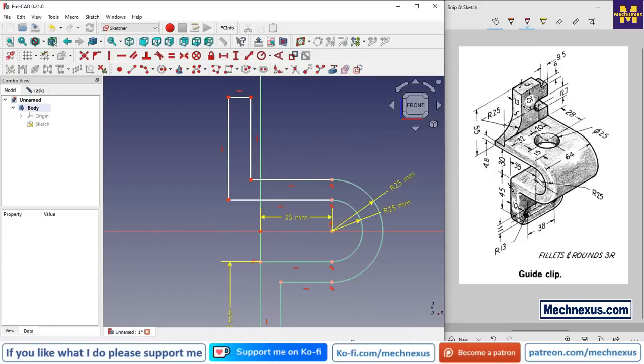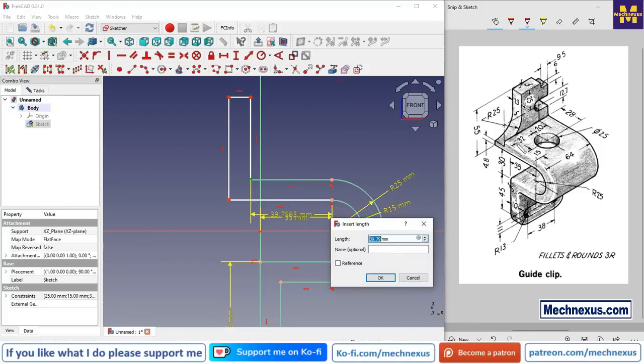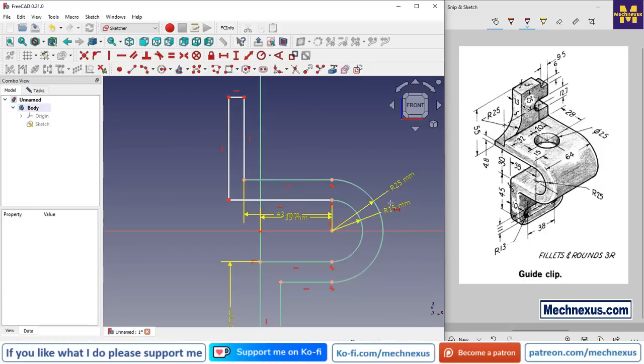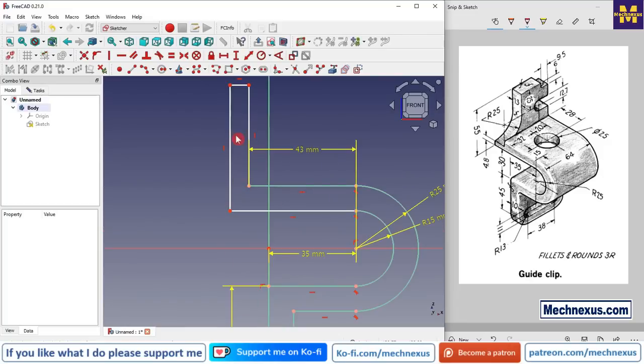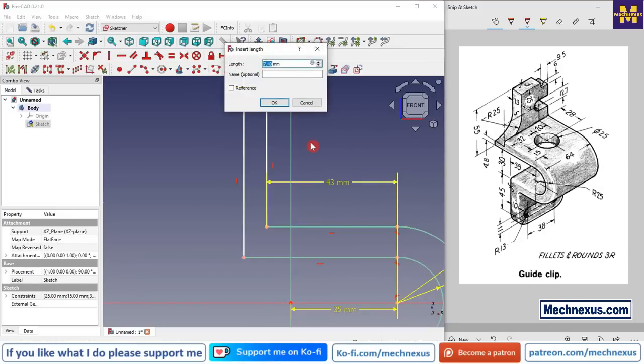And now from the center, here is a hole at 15 mm plus 28. So we will select the horizontal dimension, select this point and the origin point, and we will add 28 plus 15, 28 plus 15. And we will move it outside. And now here a 13 mm thickness is given, so we will select it and add the dimension of 13 mm.